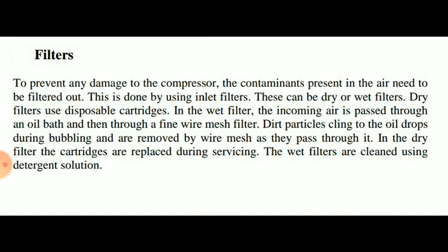In the wet filter, the incoming air is passed through an oil bath and then through a fine wire mesh filter. Dirt particles cling to the oil drops during bubbling and are removed by the wire mesh as they pass through it. In the dry filters, the cartridges are replaced during servicing. The wet filters are cleaned using a detergent solution.